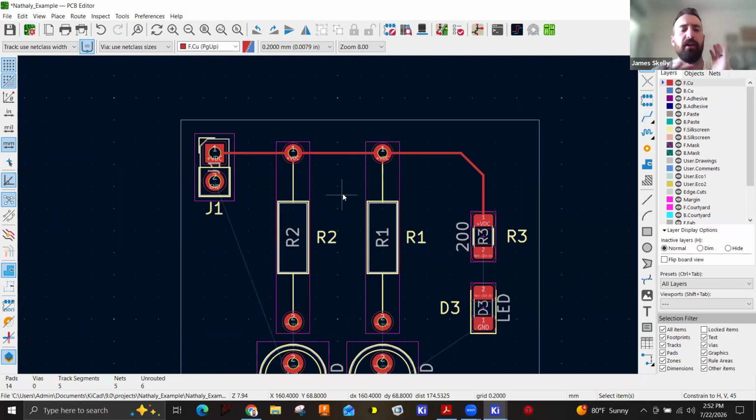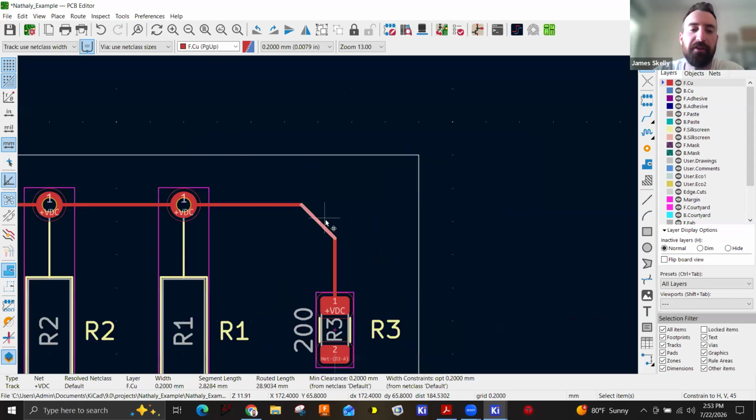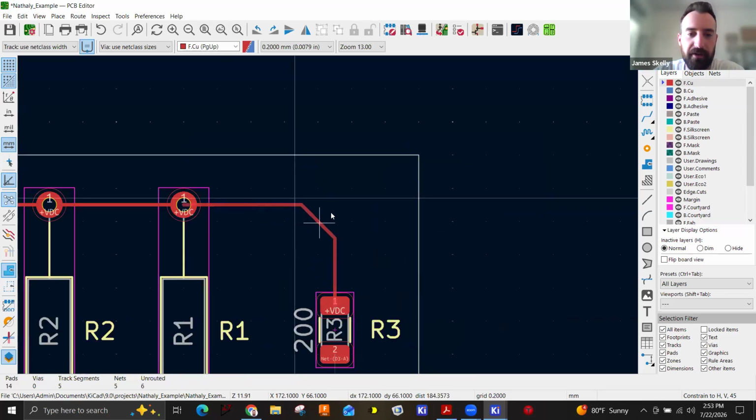It's not going to cause any errors, and the PCB will probably work. But it's been baked into my brain, so I never do 90-degree angles. It might come up one day where you end up using 90-degree angles, and I don't think it's a problem anymore. My understanding is it was a problem a long time ago, and it's since been corrected, and the fabrication facilities can handle it now. But best practice is just to use this 45 degree. Or I guess in this case, it's a 135-degree angle. Once you have the trace drawn, you can drag it to alter it.